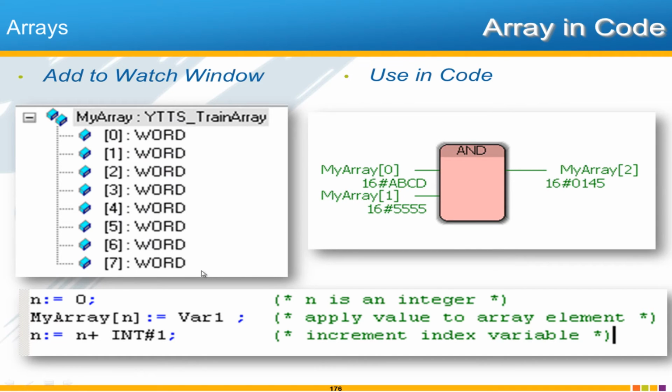And for those of you who have used arrays, I think you're already aware of this. The idea is that with this array index, it makes it very easy to, instead of using a number as I did, use a variable. So you can create an integer variable, perhaps starting at 0 for that 0 index, and then in structured text code, it's very simple to have some calculations going on elsewhere that are updating variable 1, and you're loading an array, or maybe reading from or writing, in this case we're writing to the array elements with the contents of this variable.